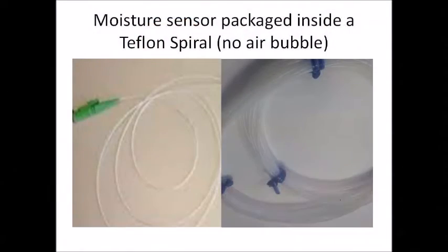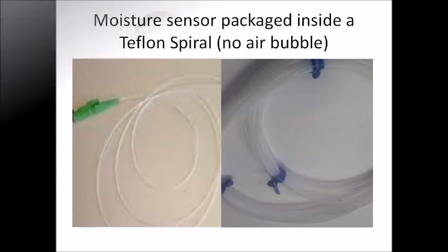Actually, it's a fiber optic sensor that can sense moisture. Moisture sensing must also measure temperature, because they are interrelated. So fiber optic nicely fits that requirement. One sensor is coated with a special material to sense moisture. Another fiber optic sensor senses temperature, which is natural. And I guess, being fiber optic, it doesn't have any issues with the high voltages. Yeah.